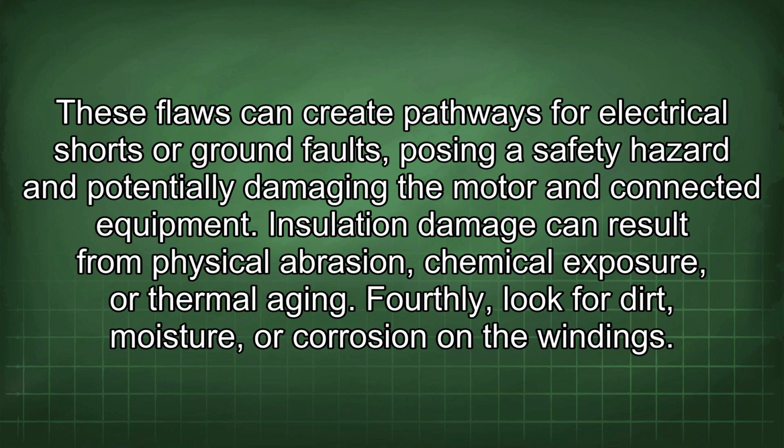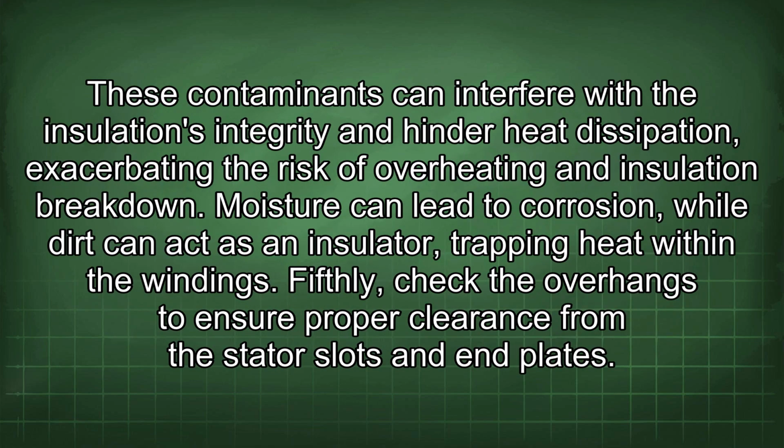Fourthly, look for dirt, moisture, or corrosion on the windings. These contaminants can interfere with the insulation's integrity and hinder heat dissipation, exacerbating the risk of overheating and insulation breakdown. Moisture can lead to corrosion, while dirt can act as an insulator, trapping heat within the windings.